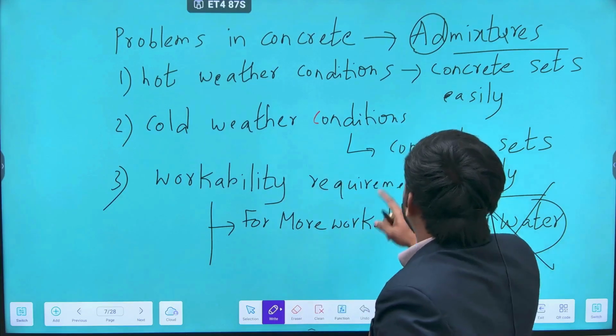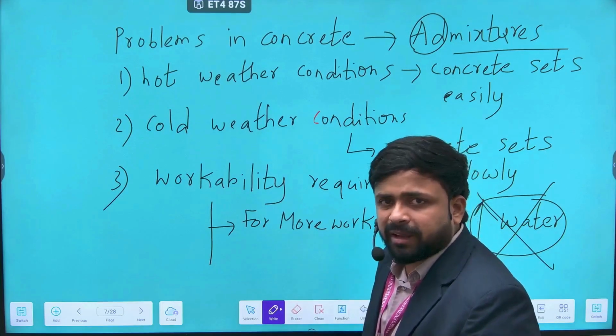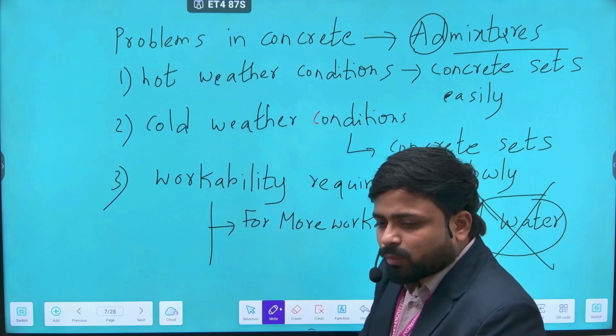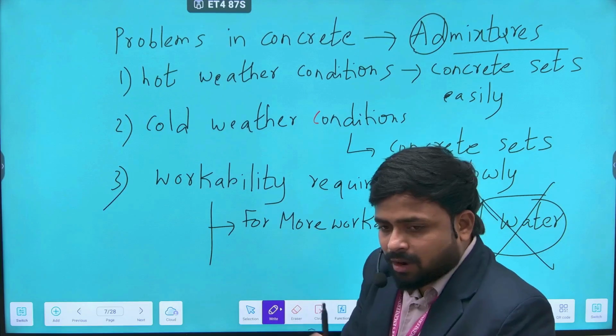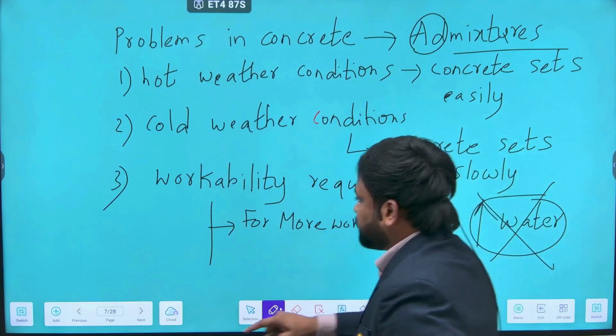In cold weather conditions, concrete is taking more than the initial setting time. That is also a major problem. So I don't want that concrete is setting too late, so I'm going for the admixture.